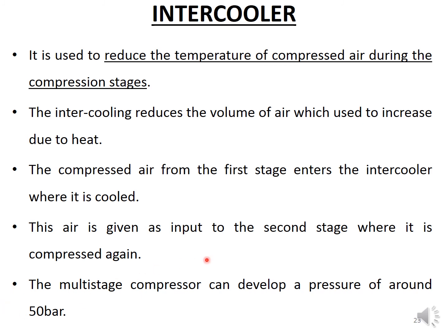If you need very high pressure, sometimes in companies there is hydrojetting and a lot of air cleaning. At that time they need very high pressure, so they have to use a multi-stage compressor. In between the stages, between one compressor and another, they use an intercooler. There are different types of intercooler: liquid cooled or air cooled, depending on the application.